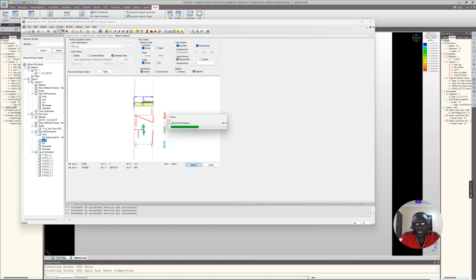That's what I saw. But if not, normally you can also do what they call an equivalent section. So you convert your irregular shape, which is not in the library of the software, for design, and then you come up with a rectangular similarity, whereby you are able to do a model using this software, and you're able to get something that will not be off the limits.